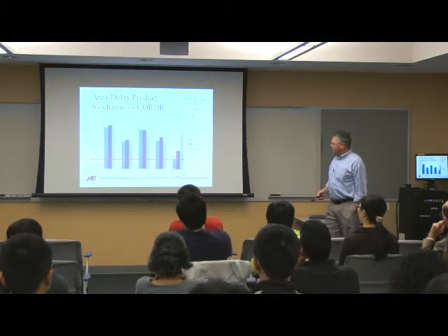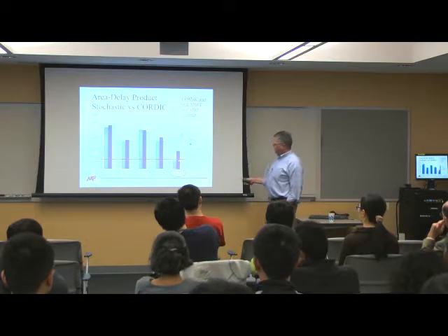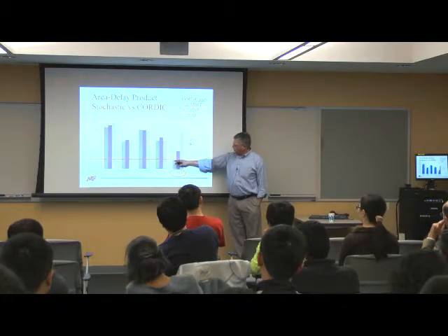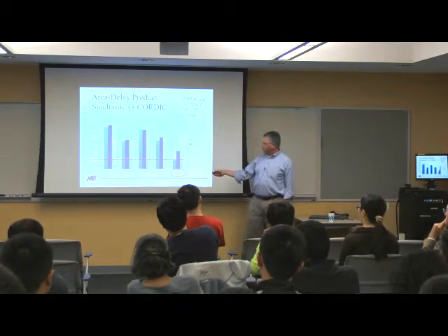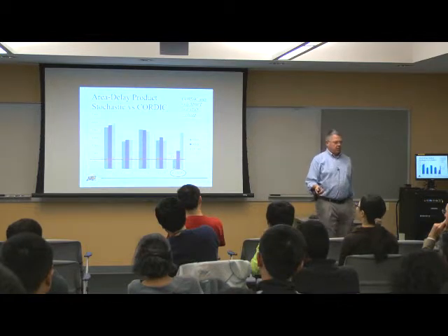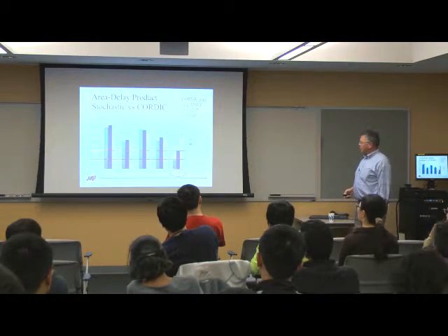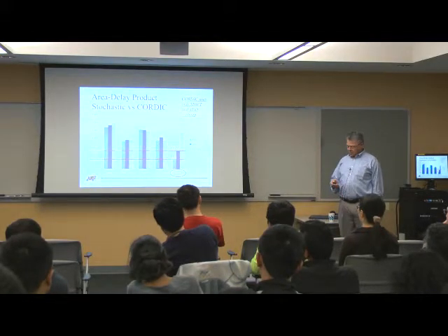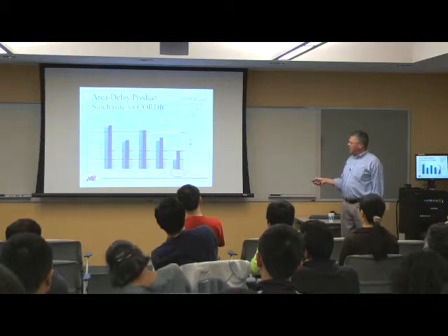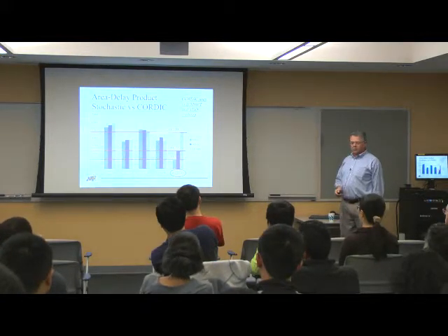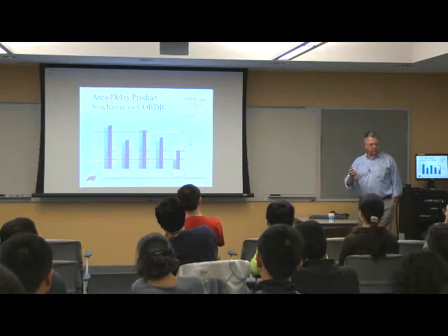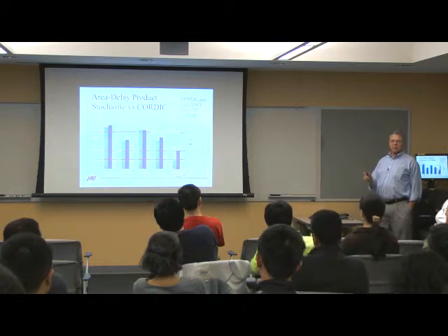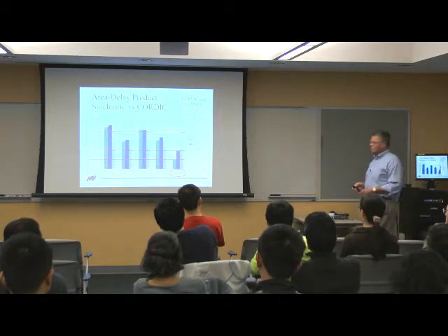And if I look at the stochastic implementation, area delay product for m equals 8 bits, I see that my stochastic implementation is smaller than any of these other 4. Okay? So it wins in this case. If I go up to 9 bits, I'm still less than any of the other implementations. By the time I get to 10 bits, then I'm better than a couple, but worse than a couple. So 10 bits for this implementation seems to be my threshold. If I need finer resolution than that, then the stochastic implementation is probably too expensive. Right.